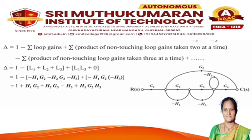Then delta is equal to 1 minus the formula. We know that delta is equal to 1 minus the sum of all individual loop gains, plus the sum of all products of non-touching loop gains taken two at a time, minus the sum of all products of non-touching loop gains taken three at a time, plus etc. Here we have only two non-touching loops. So delta is equal to 1 minus the sum of the individual loop gains L1 plus L2 plus L3, plus L1 L3, the two non-touching loops. Here we have to substitute these values to find the delta value.